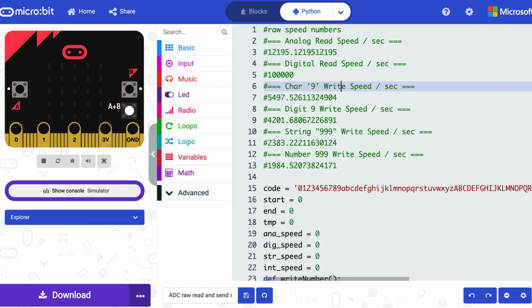However, the bigger bottleneck is here, as we were fearing. If we send out 1 byte for every sample taken, we can achieve a maximum speed of only 5,500 samples per second. But as we know, we have 10-bit data. So either we reduce that 10-bit data to 8-bit, force fitting it into 1 byte and sending it out, or we just send the data as ASCII as we have received. In that scenario, and again to keep things simple, that's what this scenario is, you will notice that the maximum samples per second that we can have is around 2,000 samples per second.